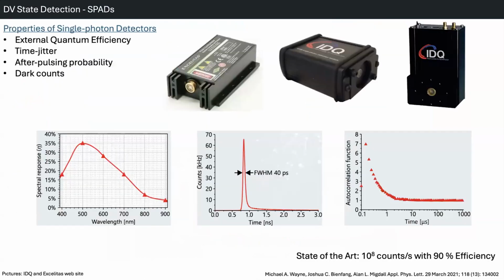I will also give you the pricing range, because you may want to implement a physical structure, for example, in your lab. It depends. It begins from 5,000 euros to 12 to 15,000 euros, even for these devices. Because if you go to a very precise timing resolution and high quantum efficiency, then you will need the best of the best diodes. And diodes, when they are produced in a wafer, are produced like thousands together, and you pick only the good ones. So you are paying the price to pick the good ones from the production.